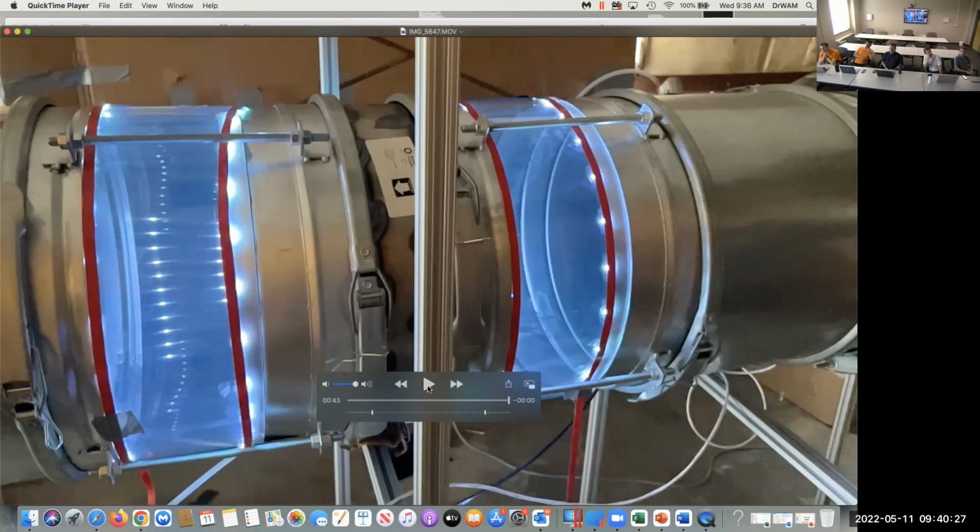Okay, gentlemen, so you see what we have accomplished. We have a test stand set up. I have a young man who wants to go to grad school for his master's, and we're going to use this to try and do a more thorough study where we're going to look at the equivalent length downstream of that blender where the irrotational flow goes away. That comes into play in terms of accurate pressure measurements. This is something Mark Pavot pointed out to us. We're going to take a look at what is the pressure drop across this blender.